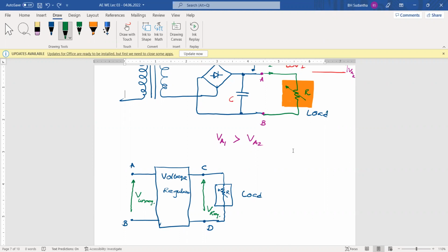But your power supply is a very cheap one. There is no inside voltage regulator. Because of that, it cannot provide a regulated 12 volts output all the time. Depending on the amount of current your organ is taking, your power supply is reducing the voltage. Much more current taken, less voltage. Less current taken, higher voltage. Like that, you have different voltage provided to the electronic organ from time to time, depending on the current you are taking.